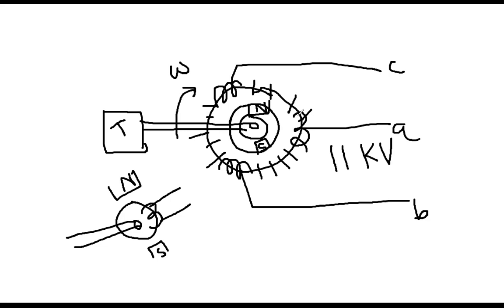That's why in the synchronous generator, the coils mounted on the armature body remain stationary, static, and you have to rotate the field. You have to rotate at least one thing, either the field or the coil. That's the voltage generation principle, like Fleming's right hand rule. Everybody knows, if both remain static, there will be no voltage. If both move at the same speed, no voltage. There should be relative motion.